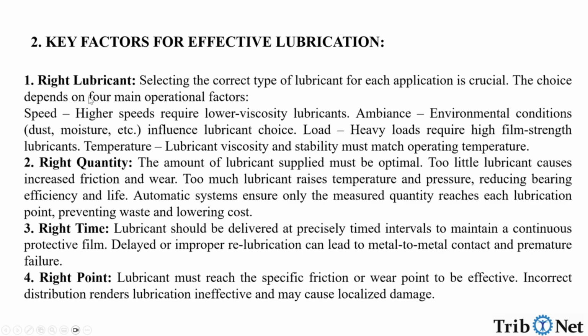The right lubricant. Selecting the correct type of lubricant for each application is crucial. The choice depends on four main operational factors, that is, the speed, which is higher speeds require lower viscosity lubricants; ambience, that is, the environmental conditions like dust, moisture, etc. influence the lubricant choice; load, that is, heavy loads require high film strength lubricants; temperature, lubricant viscosity and stability must match the operating temperature.